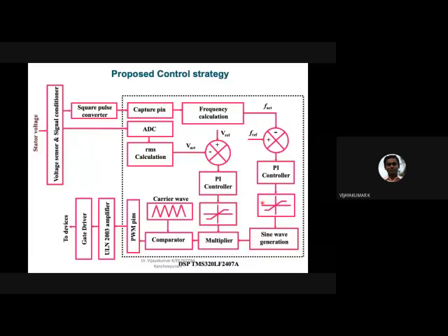as a signal from the system, then in that sine wave itself you will have a lot of harmonic terms. Those harmonic terms again give harmonic terms in the signal. So whatever voltage you are generating from that inverter, that voltage will also consist of harmonics. So if you are generating your own sine wave, that means a pure sine wave.